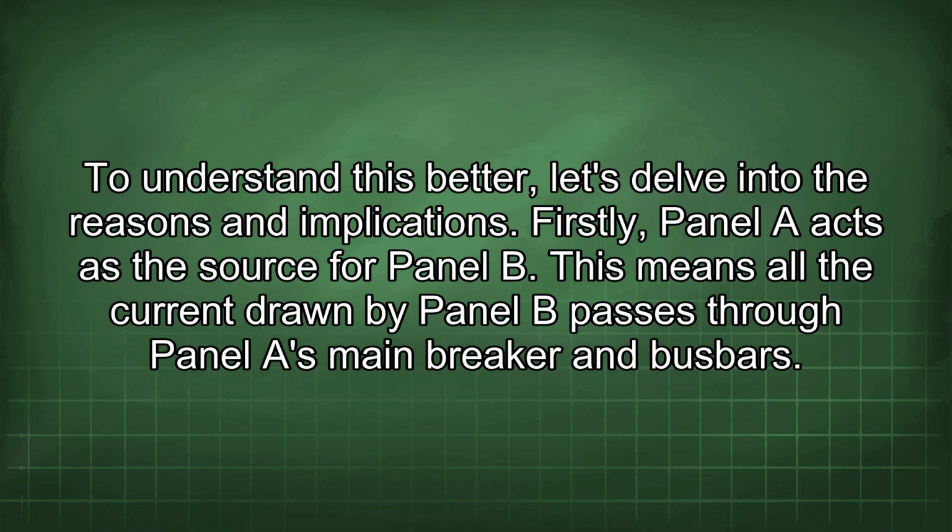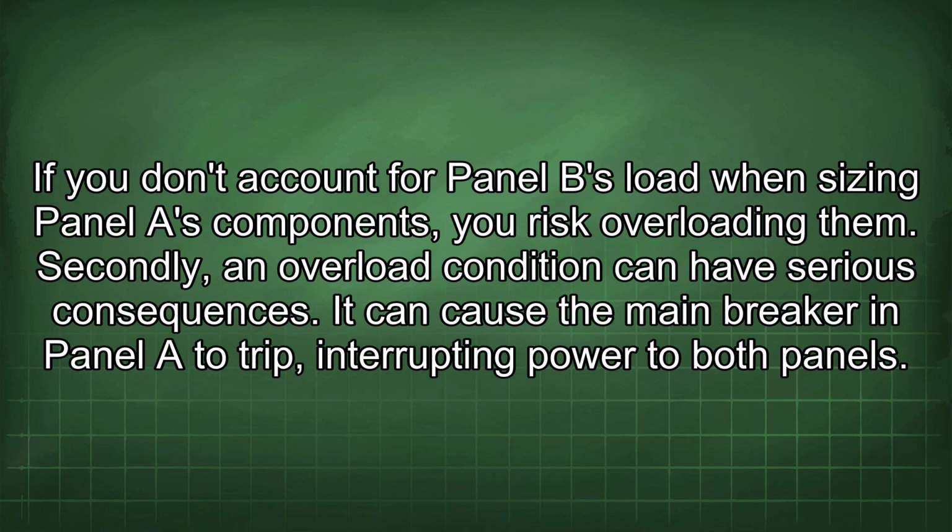Firstly, panel A acts as the source for panel B. This means all the current drawn by panel B passes through panel A's main breaker and busbars. If you don't account for panel B's load when sizing panel A's components, you risk overloading them.